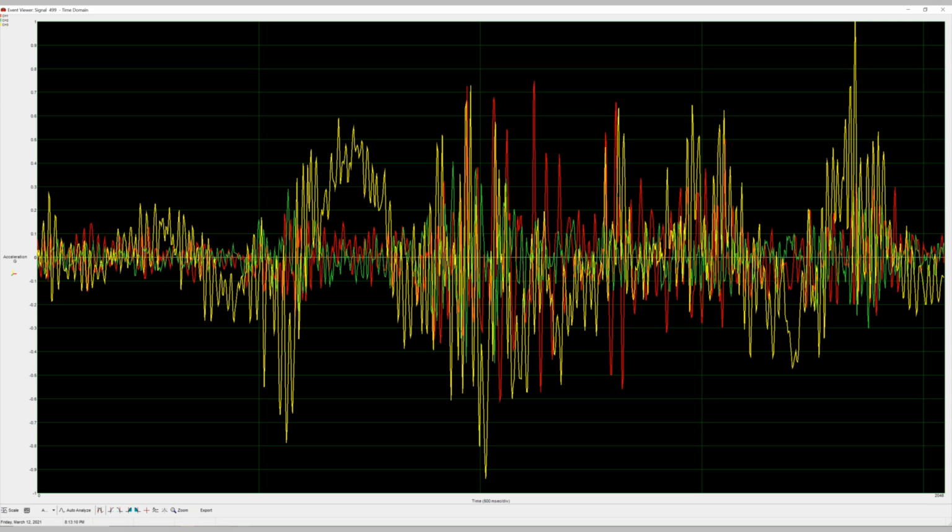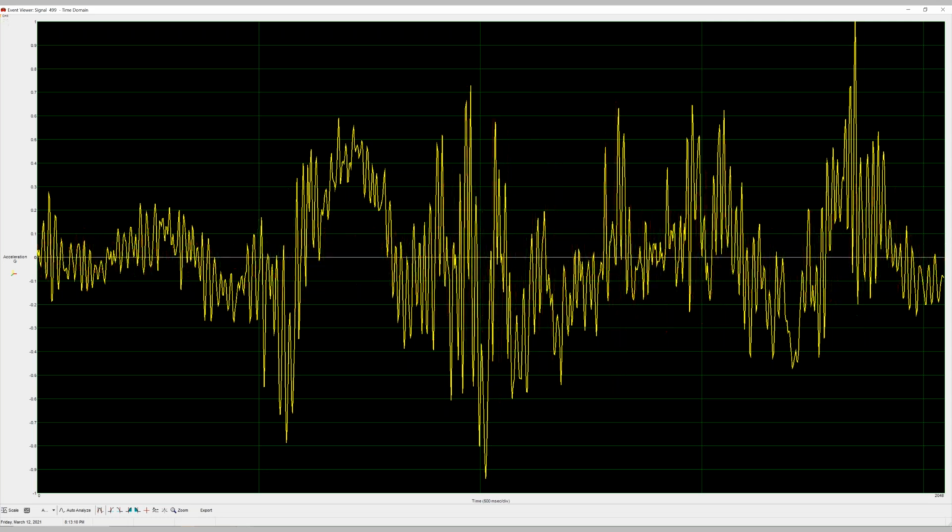So there's a lot going on there, but if I focus right on just the vertical vibration, which in this case is the most intense vibration that you experience on the back of a truck, and which is what is performed for the majority of testing that's performed in a laboratory, it's vertical vibration testing. So I'm going to focus just on this vertical signal.